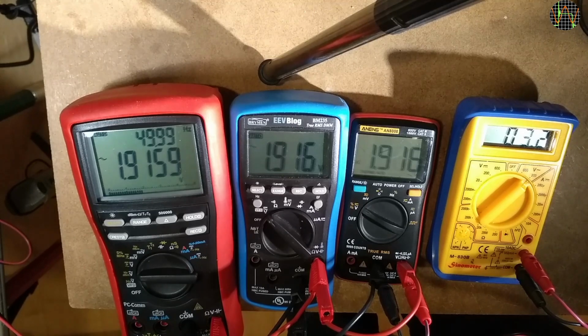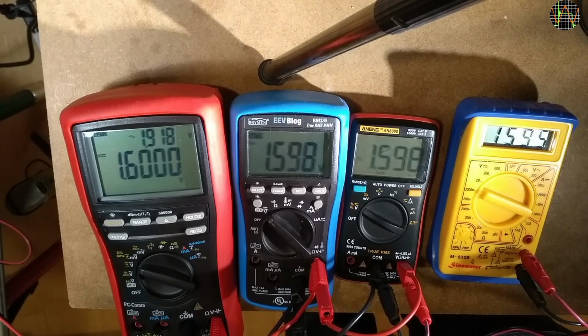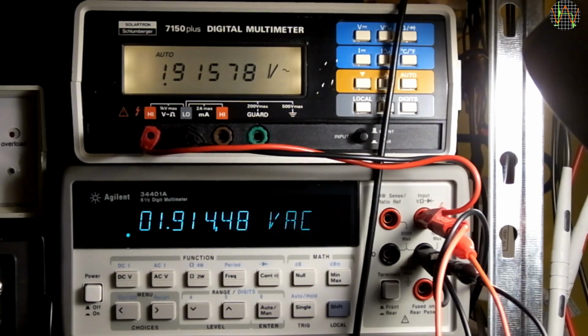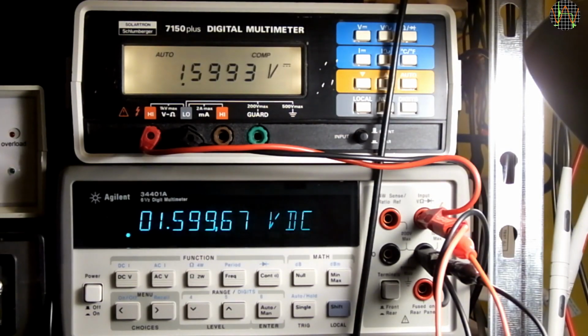about 1.91 volts, which is quite different from the scope value of 2.5 volts, while the yellow multimeter shows 3.2 volts. On the DC side, all meters agree with the average value of around 1.6 volts shown on the scope. Again, the BM869's AC plus DC display of 2.49 volts matches the RMS value shown by the scope. And the bench meters repeat what the handheld meters were showing, 1.9 volts RMS and a DC value of 1.6 volts.